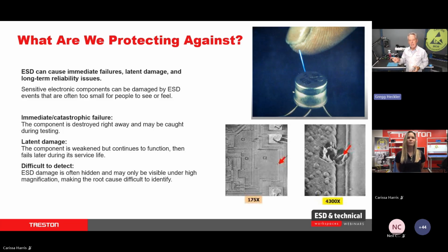Now, the big difference here is we have a workstation here with a grounded static dissipative mat on it. So I'm going to show you this charge again real quick. Now I'm going to set my plastic case on here, and I'm going to ground that charge. Did I ground that charge, Henry? No. No, right. So now I'm going to take my conductive paddle, and let me show you the charge here. Okay. Now I'm going to ground that conductive paddle or my board or my IC. Did I knock that charge down, Henry? Okay. So you can ground conductors.